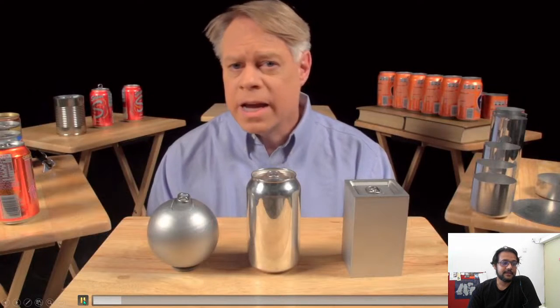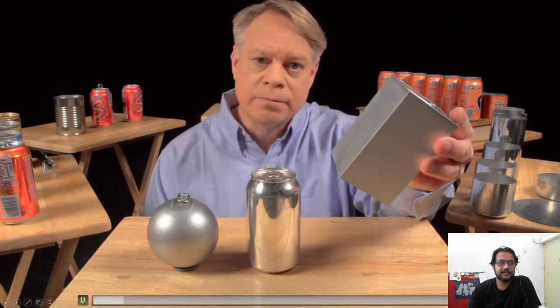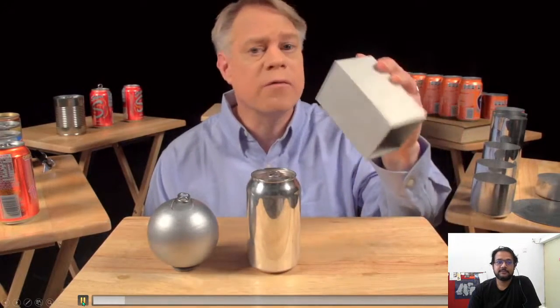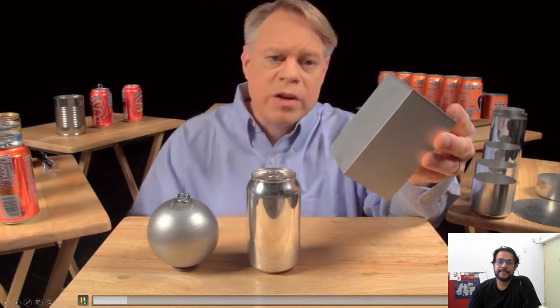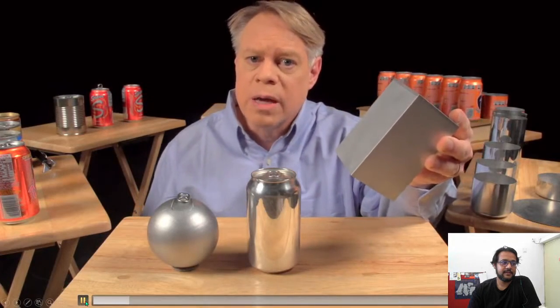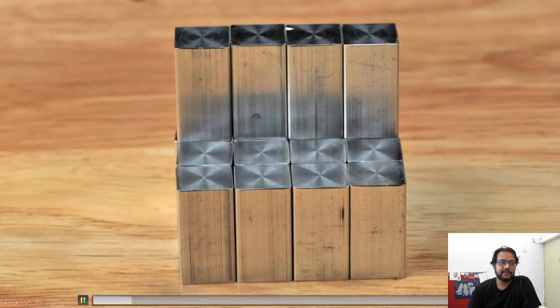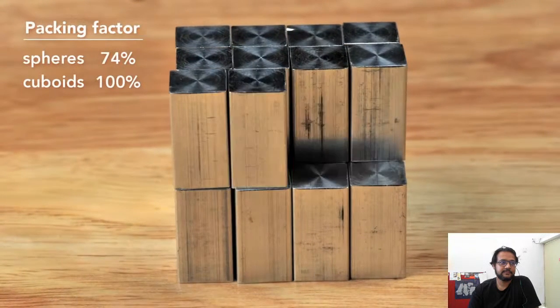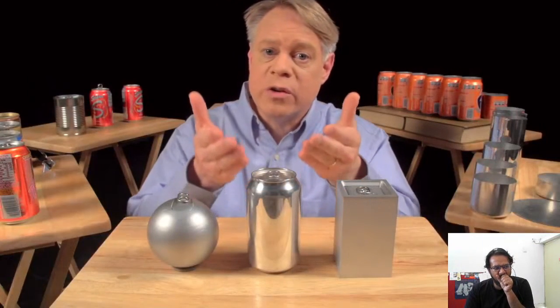An engineer could solve this problem by making a cuboid shaped can. It sits on a table, but it's uncomfortable to hold and awkward to drink from, and while easier to manufacture than a sphere, these edges are weak points and require very thick walls. But the cuboid surpasses the sphere in packing efficiency. It has almost no wasted space, although at the sacrifice of using more surface area to contain the same volume as the sphere. So, to create a can, engineers use a cylinder, which has elements of both shapes.